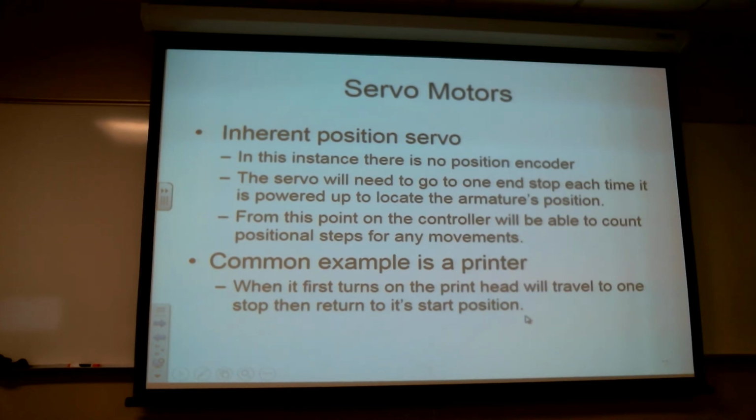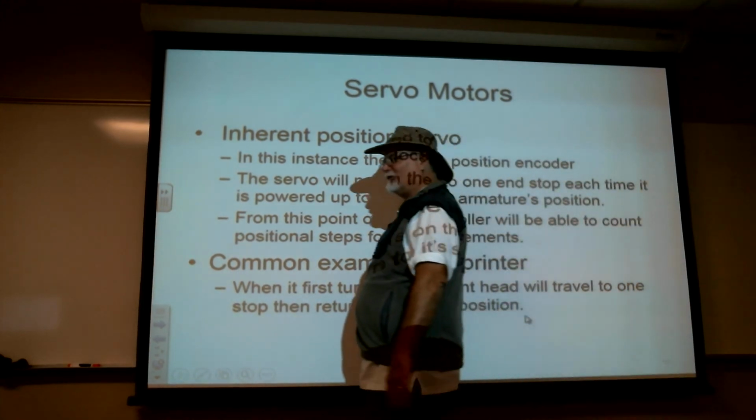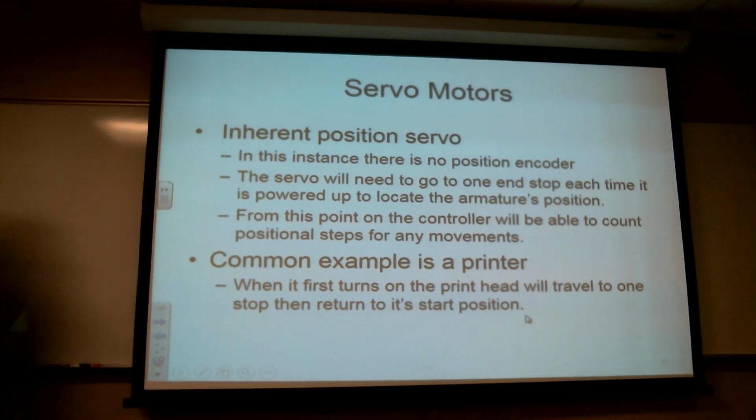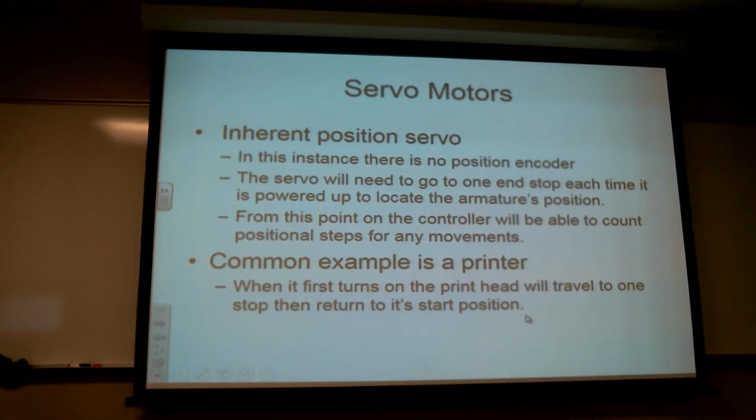When you go like that, and what's up here, it still comes all the way till it hits the encoder. It's usually just a switch that says stop. That's a really early example of this kind of setup. It, in fact, is a servo that is internally encoded. It only has one position encoder, but that's okay. As long as it always comes to home and sits there, then it'll always be starting from there. And yeah, you can get them installed incorrectly.